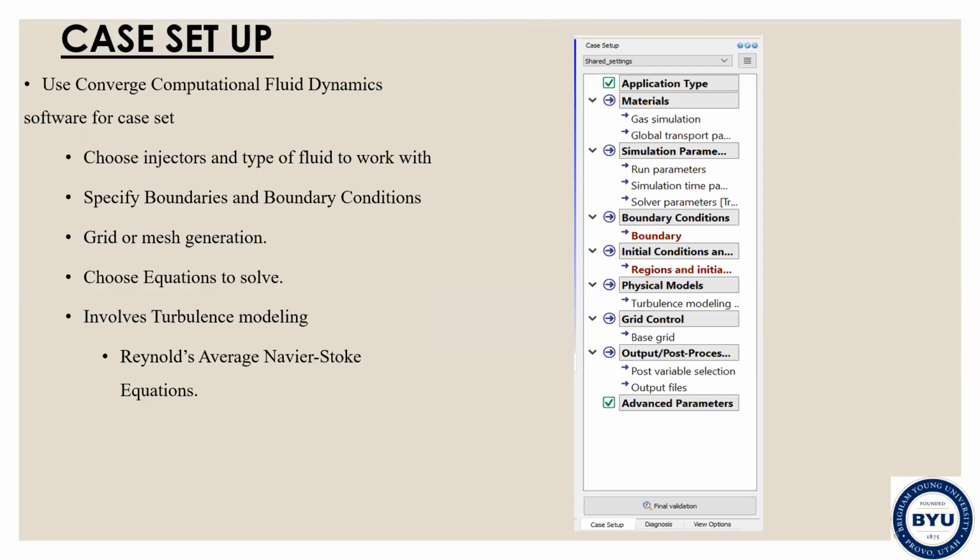After using the CAD, I use SolidWorks to build that geometry. I import it into the Computational Fluid Dynamics, or CFD, software that I use. It is called Converge, and that is what I use to build the case setup. I define the injector that I want to use. Another important thing that I also consider is the boundary conditions, the flows and the pressures at the inlet and then the outlet, and also the wall. We specify whichever conditions that we want to put over there. To my right hand, over here, that specifies the various parameters that I'm supposed to input when I'm doing the case setup.